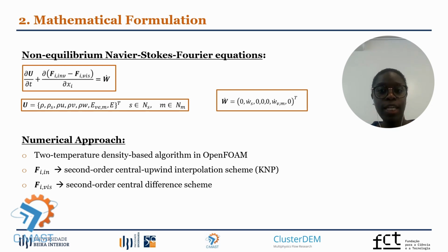For that reason, in addition to solving a total energy equation, we also solve a vibroelectronic energy equation, a total mass conservation equation, a mass conservation equation for each species, and the three momentum conservation equations. The source term here corresponds to the mass production of species due to the reactions, and also the term responsible for the energy transfer between the vibroelectronic and transrotational energy modes.